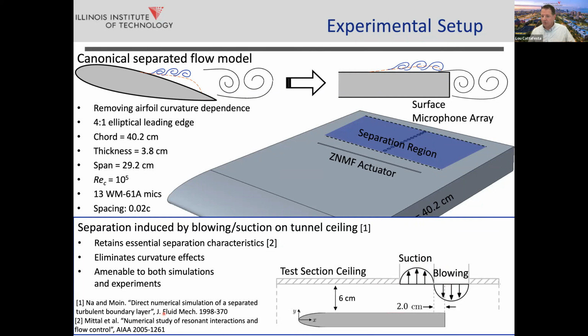So it produces a very canonical separated flow that enables you to study this in a framework that enables computations. So for example, my colleague Rajat Mittal at Johns Hopkins does large eddy simulations, and he could use essentially rectilinear grids that are highly clustered near the wall with great ease and go to reasonably high Reynolds numbers that match what we have in the experiments, at least for large eddy simulations. So that was one of the motivations for doing this.